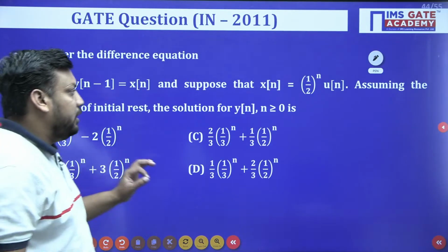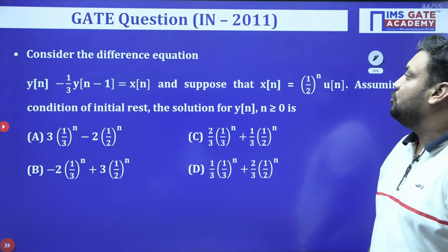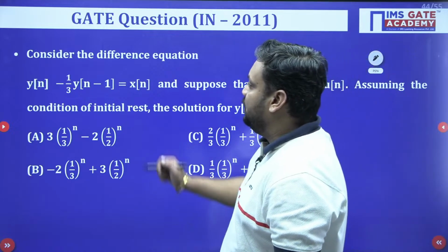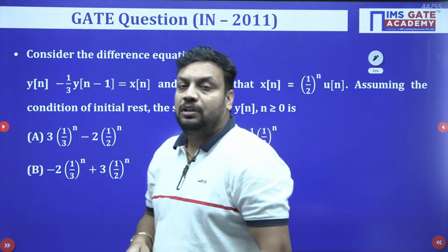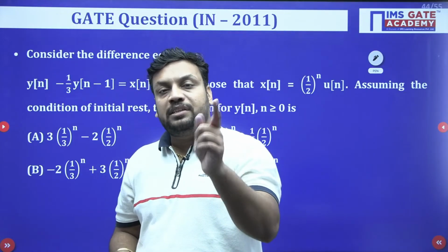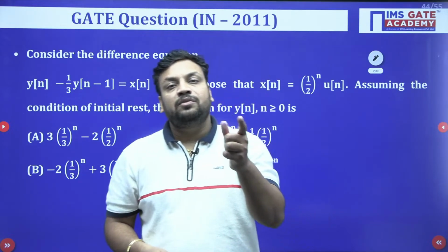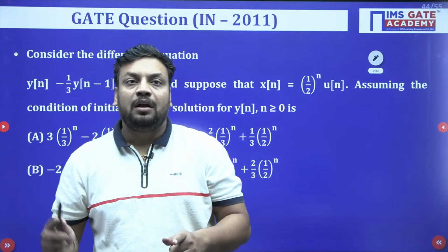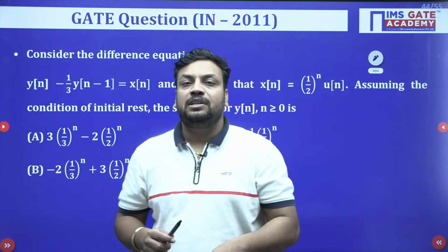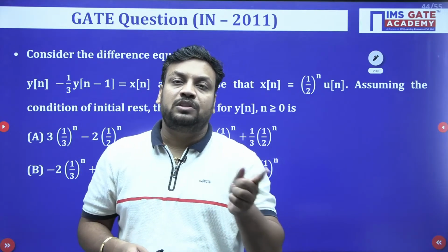Now, in today's class, we are supposed to start with this GATE question. This GATE question, Instrumentation 2011, just read the question, guys. Consider the difference equation. As I told you in the last classes, whenever any differential equation is given to you, the first step is always to take the Laplace transform both sides to find the transfer function. But whenever any difference equation is given, we have to take the Z transform both sides to find the transfer function.